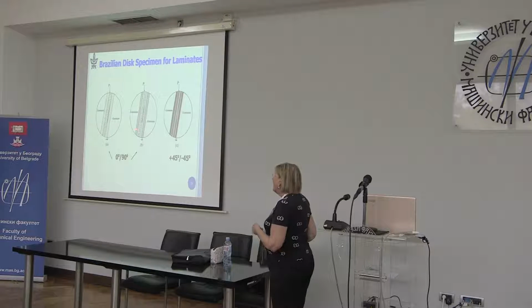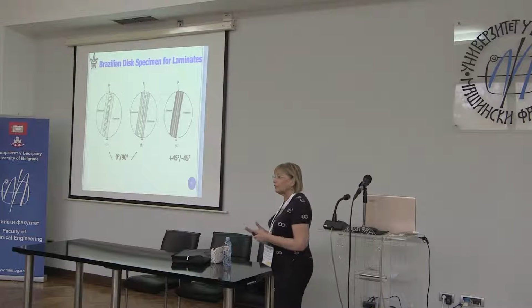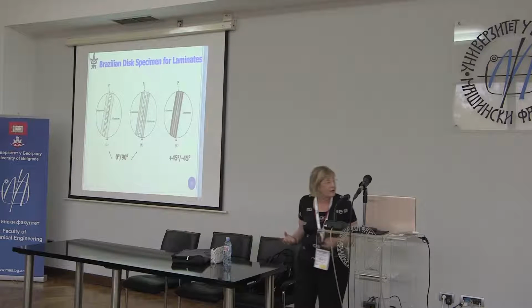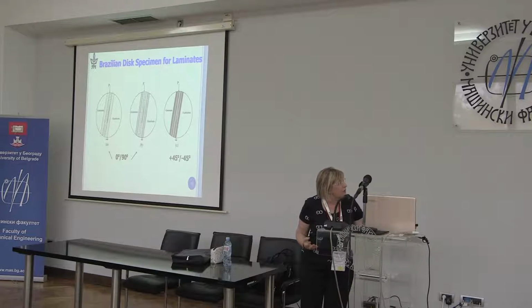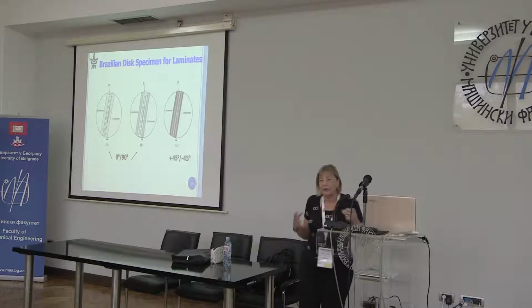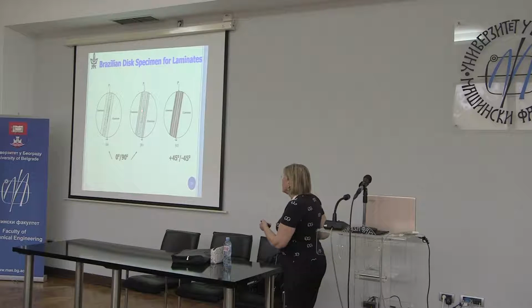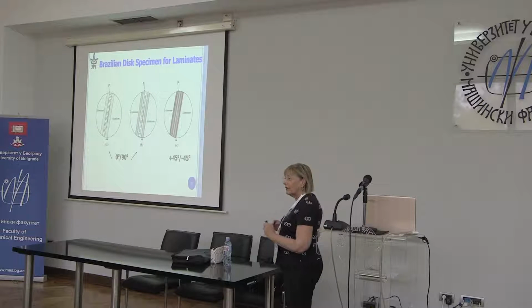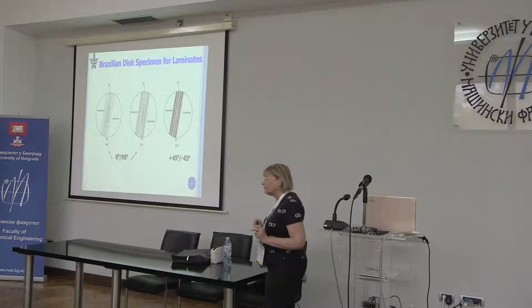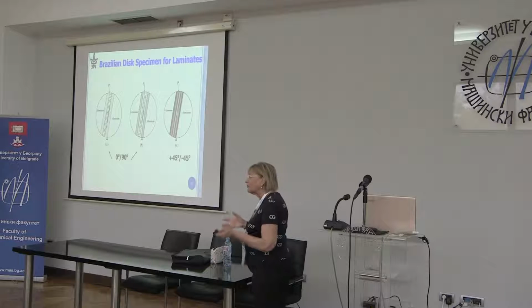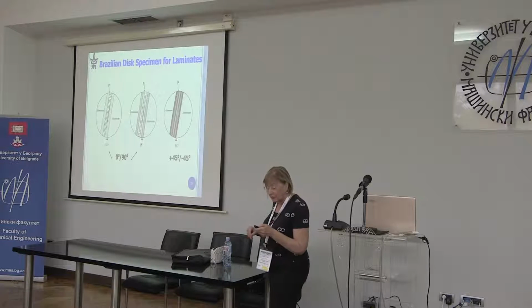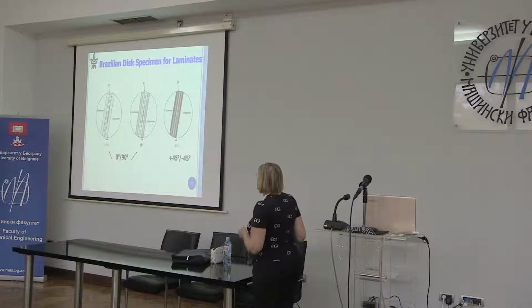So, of course, theoretically, these two layups should give you the same results, otherwise you don't have a fracture toughness parameter. This is 1/2 millimeter each of the plies, and this is 4 millimeters. If fracture mechanics really works here, then you should get within the scatter the same results. So I didn't sleep until we did about 10 specimens and analyzed them and saw that they do give us the same results. But there were a number of sleepless nights.